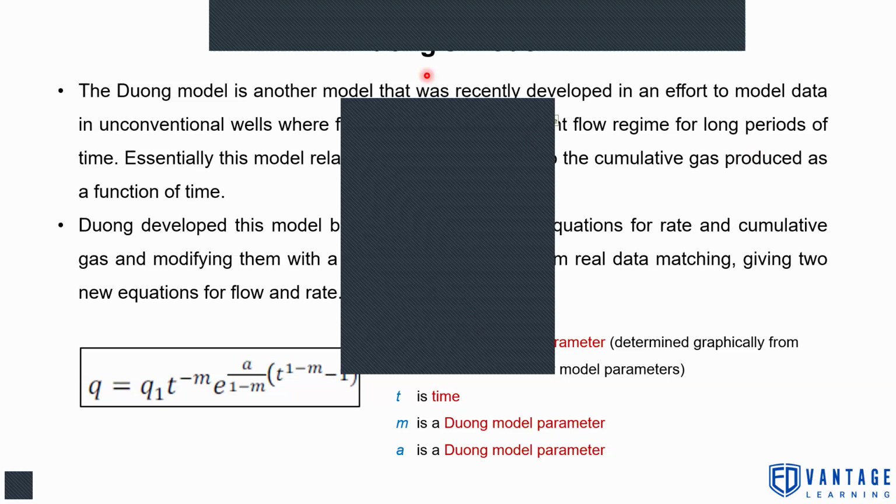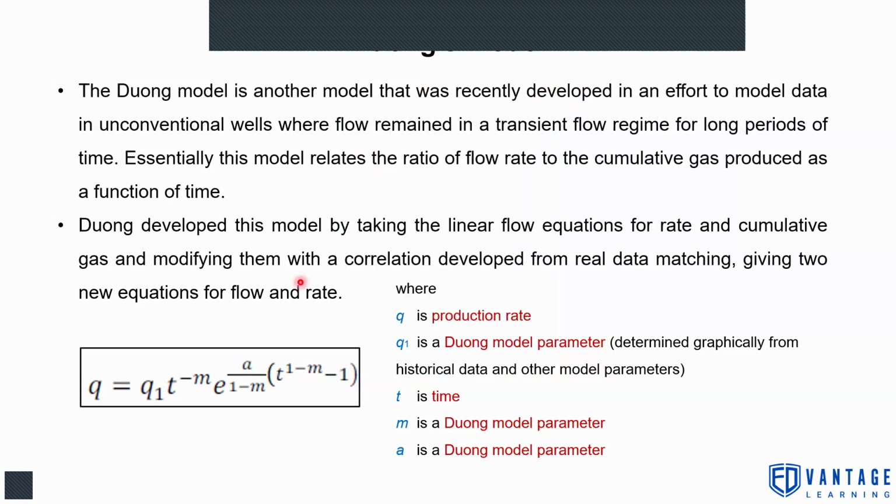Someone, Shubham Gupta, answered that dP/dt is not constant in transient flow regime. We cannot say that dP/dt is not constant, but we can say that at the reservoir boundary, the pressure keeps on increasing. We cannot estimate where the boundary is in transient flow regime. So transient flow regime has two conditions. At r equal to re, when the radius reaches the reservoir extent radius, P will still be increasing. So the boundary is not felt in transient flow regime.